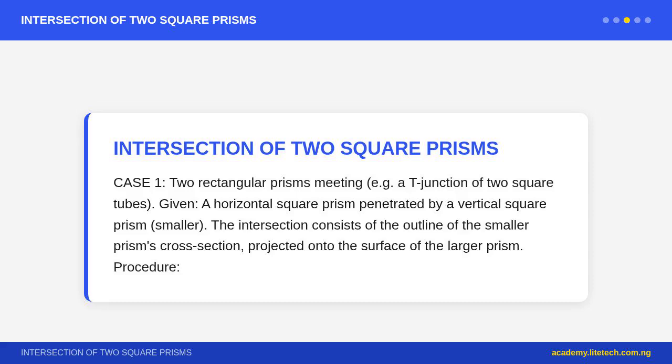Case 2. A horizontal cylinder penetrated by a vertical square prism. Method using generators, longitudinal lines on the cylinder surface. Step 1. In the front elevation, draw the square prism penetrating the cylinder. Mark several horizontal generator lines on the cylinder, lines parallel to its axis. Step 2. In the plan end view, each generator line appears as a point on the circle. The square prism appears as a square. Mark where the square's edges intersect each generator.